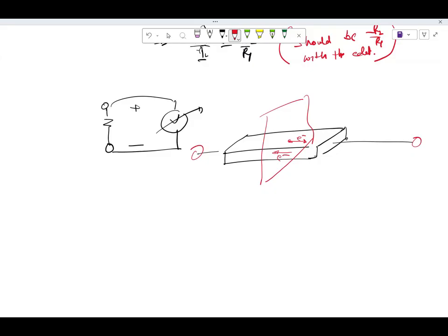Obviously, if you put some voltage, net current will flow, then you are going to see an average one direction movement. But under this condition that there is no excitation, then in an instantaneous sense the number of electrons moving towards one terminal will be different from the number moving towards the other. On an average, it will still be zero, and has to be because current is zero.